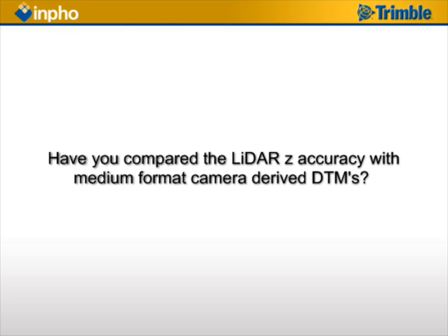Again, it depends, of course, on the flying height that you have. So there's a geometric component that you have to look at. In any case, in the data that we have investigated so far, we have seen that, as I was saying about the noise in the point cloud, we have from imagery a better noise ratio than what we have from a laser scanner. So in these terms, you could say that in some cases you even have a better height accuracy than what's coming from a laser scanner.